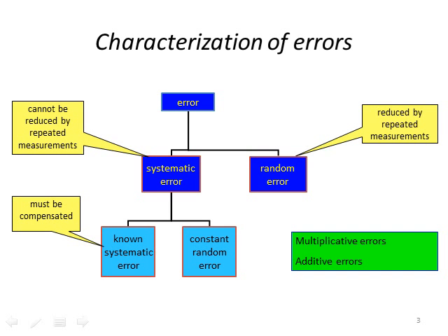Now, random error is something we always have in our measurements. We can reduce it by doing repeated measurements, but we will always have some sort of random error. We can never really completely get rid of it, which is different than a systematic error. Usually a systematic error, we can do some correction in how we're doing the measurement. If we have some offset in our operational amplifier, we can tune the offset parameter of the operational amplifier to get rid of that systematic error on the output. However, the random error on the output is always going to be there.